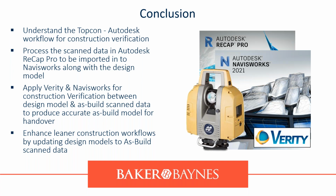Once that's done, we applied Verity to pick up the tolerances or the differences and verify the 3D scanned as-built state versus the design build state. And once we were able to pick up these discrepancies, we could have updated it to create one consolidated model for as-built handover, right? So what this does is it enhances much leaner construction workflows by updating the design models to as-built scan data.